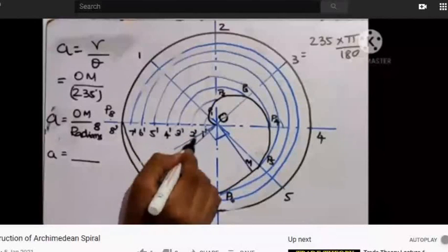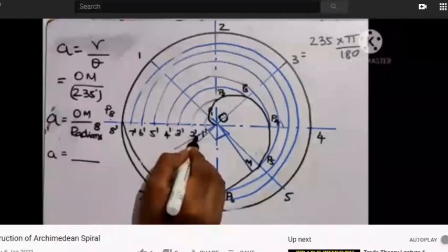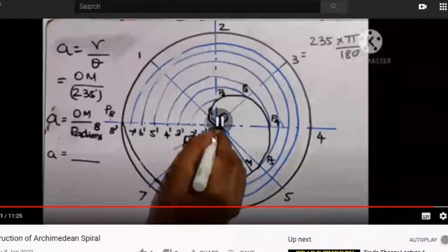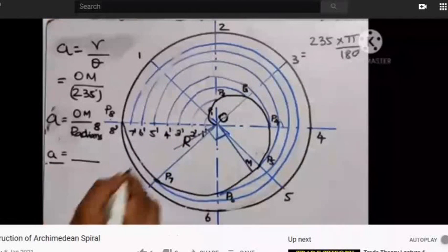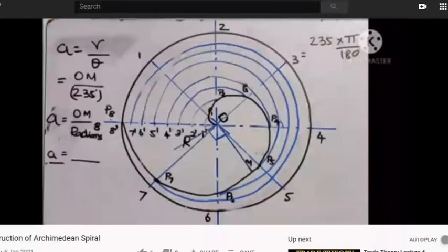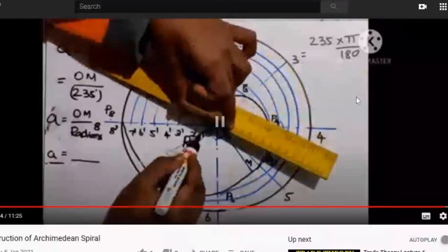So in this line, you need to mark that 9.5 mm. Let's take this as R, capital R. So the distance between OR is nothing but this calculated constant A. You need to mark this. So the next step is you need to draw the normal. From R, you need to connect M. So that is your normal, and if you draw a perpendicular to that, that will be your tangent. Okay, is that clear?